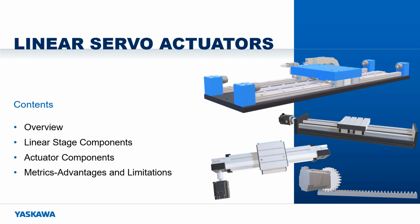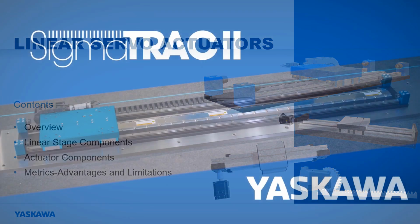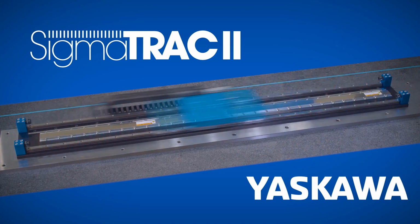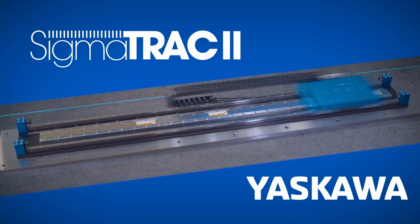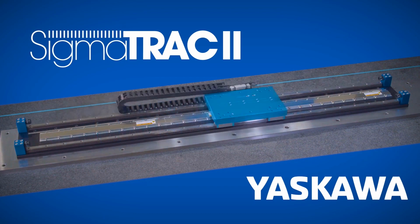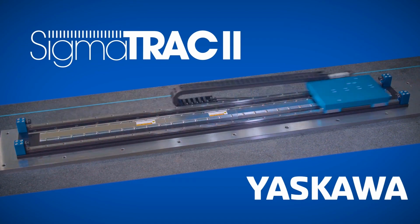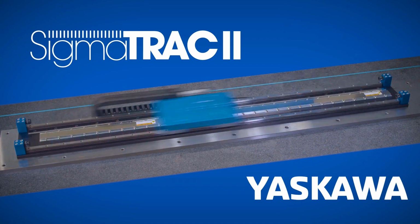The advantages and limitations of each mechanism are crucial when deciding how to apply the technology. By the end of this video, I expect you'll be able to more readily identify linear motor applications that may otherwise have been solved less effectively with a different mechanism. I'll start with a summary of what I mean by a linear motor stage, using Yaskawa's Sigma Track 2 as an example. The distinguishing feature of a linear motor is that the load moves without any mechanical power conversion. The linear force generated by the motor coil is directly connected to the load.